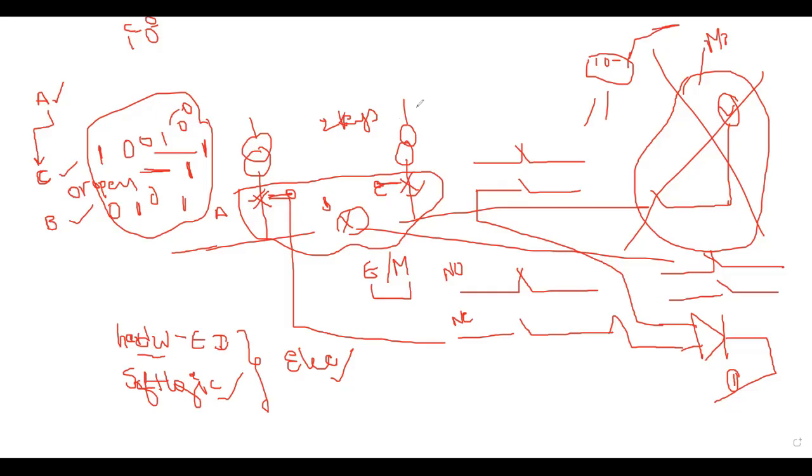Suppose tomorrow this transformer has failed and this breaker was opened. So I will remove this key, and I will place the key here and I will close this. So again, this breaker and this breaker are in closed position. So this is a mechanical way of interlocking.